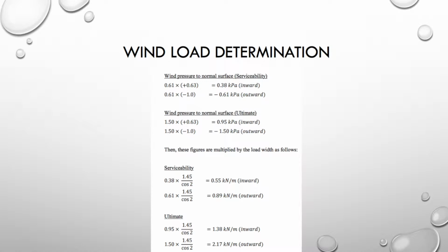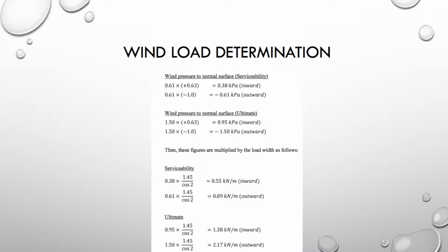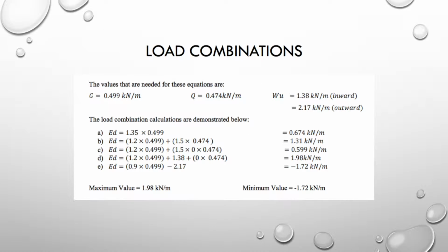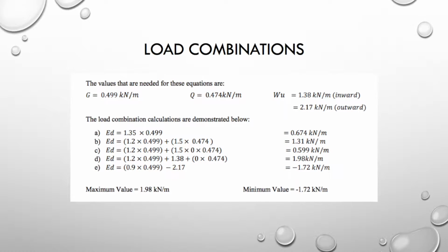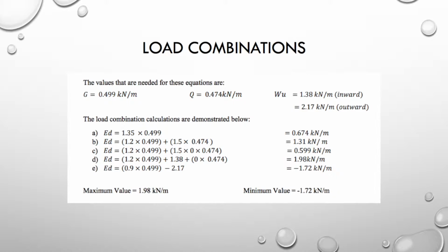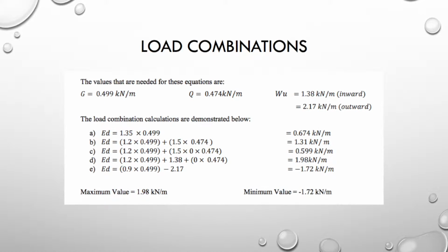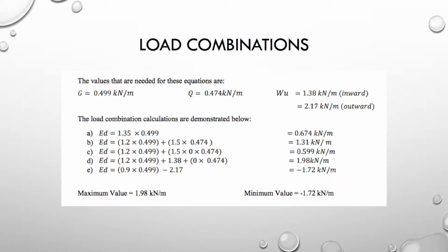The domestic shed that is the subject of this report is in Wind Region A, which is a non-cyclonic wind region. The structure falls under terrain category TC3, with numerous closely spaced obstructions surrounding the structure. By using the variables of wind region and site conditions, engineers can refer to the tables in AS 4055 to determine the wind classification for the structure.